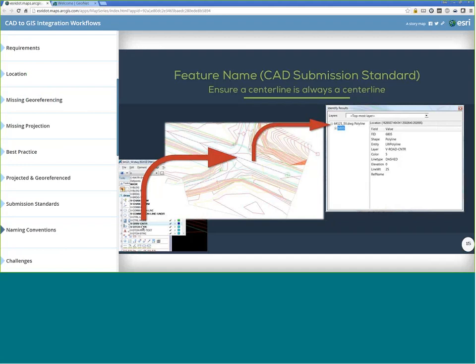And you can see the layer names. I'm looking at the layer names in MicroStation. And for instance, the center line is called V-DRIV-CNTR. So that indicates it's the center line. When I convert this and bring it into ArcGIS, the layer name comes through perfectly.